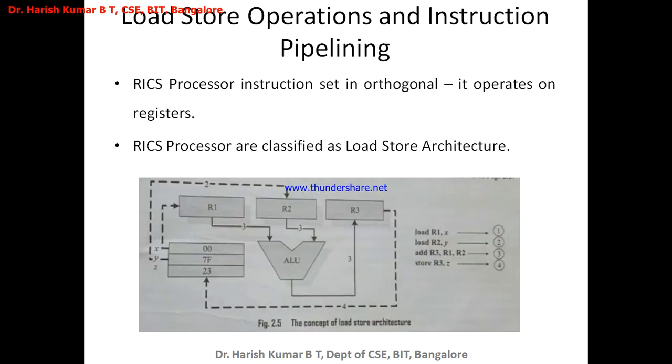Okay, now load, store operations and instruction pipelining. The RISC processor's instruction set is orthogonal in nature. That means it operates only on the registers. It performs the data processing of the operands only on the registers. And the RISC processors are classified as a load and store architecture. RISC processors will not come under the register memory class of architecture.